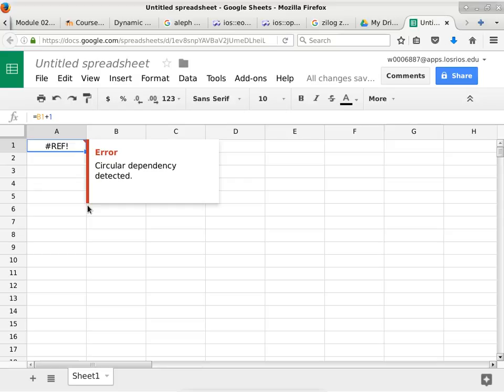When you look at the adder circuitry, it doesn't have any type of dependency like that. And if you use an SR latch the right way, it doesn't generate this problem either, because once it is in a state and a particular pin settles, it doesn't change anymore because of another gate that was affected by it in the first place. So I think that is how it works. It detects that circular reference, says we have an oscillation problem, but it's not going to simulate the oscillation itself.